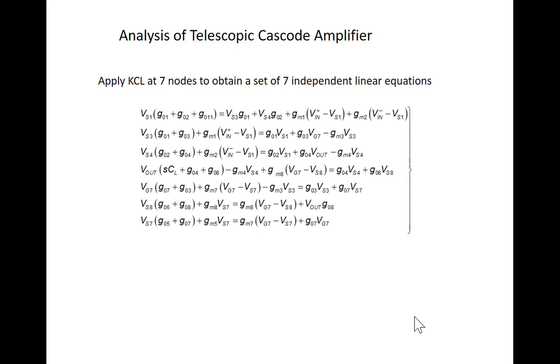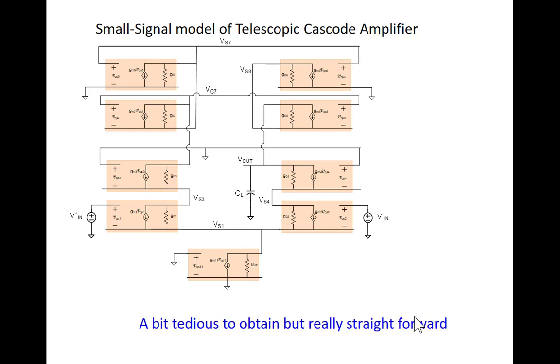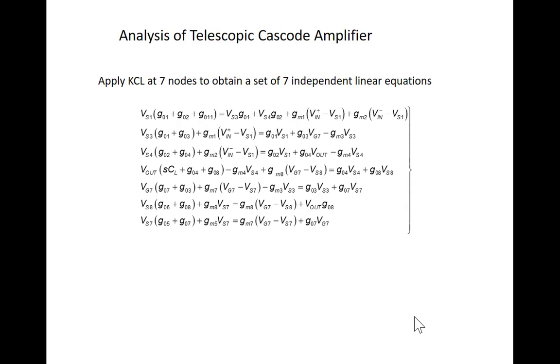And if you look at this circuit, I have non-critical nodes at the top, here, here, here, here, and here. So I have 7 critical nodes, 7 nodes in the circuit that are not an input. So I can sum currents to those 7 nodes using Kirchhoff's current laws, and I get these 7 equations. And I made a mistake or 2 on these because I was probably thinking about something else when I wrote in the equations, but I finally cleaned them up.